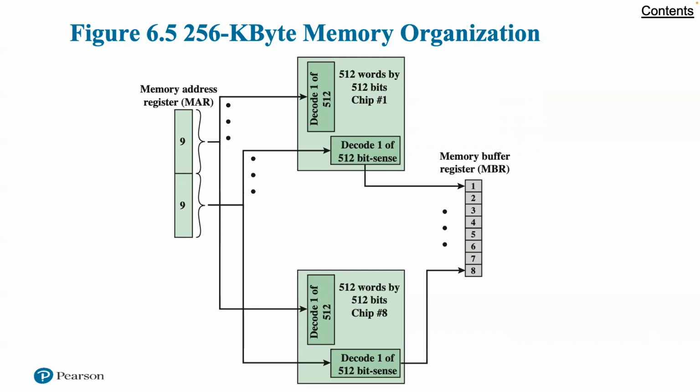For 256K words, an 18-bit address is needed and is supplied to the module from some external source, i.e. the address lines of a bus to which the module is attached. The address is presented to 8 individual 256K times 1-bit chips, each of which provides the input and output of 1 bit.